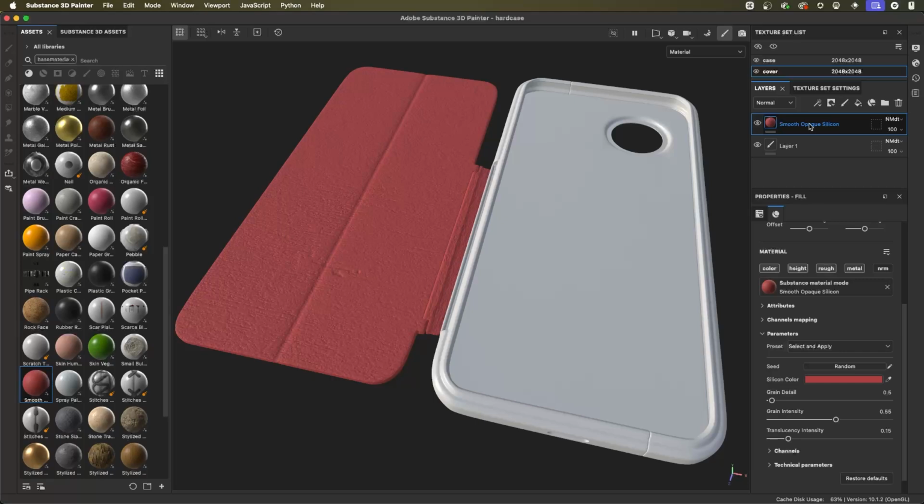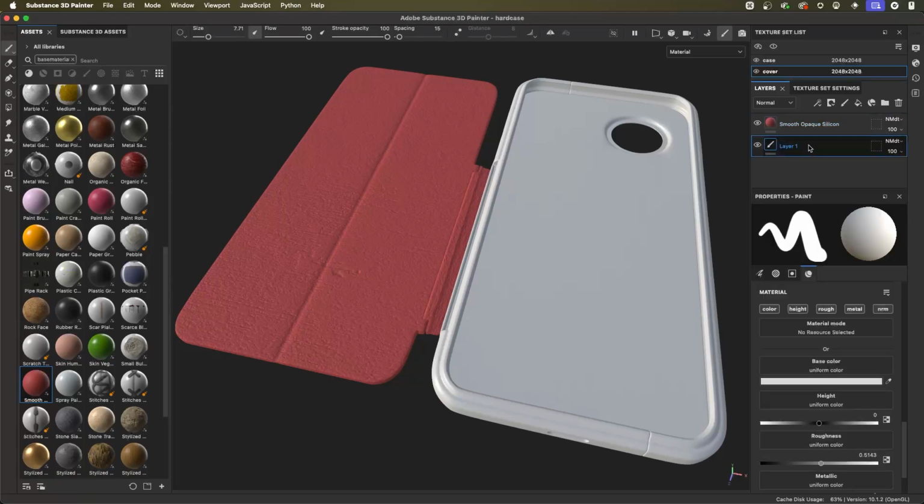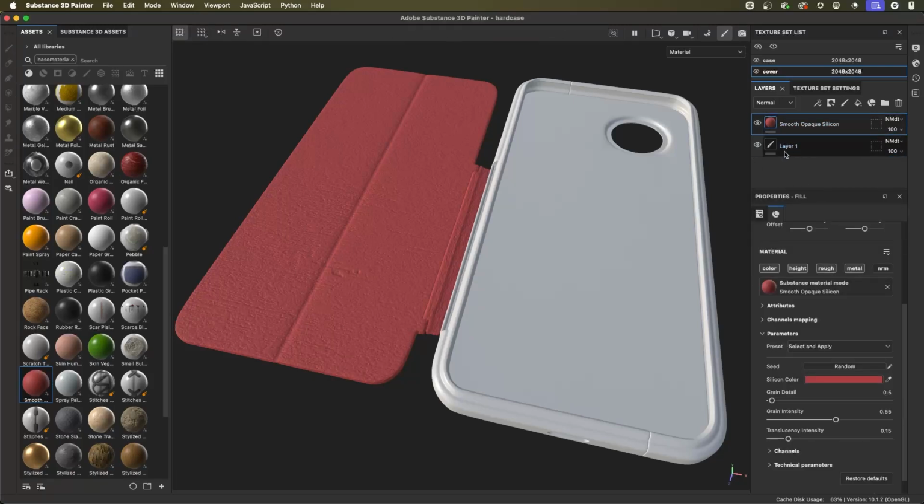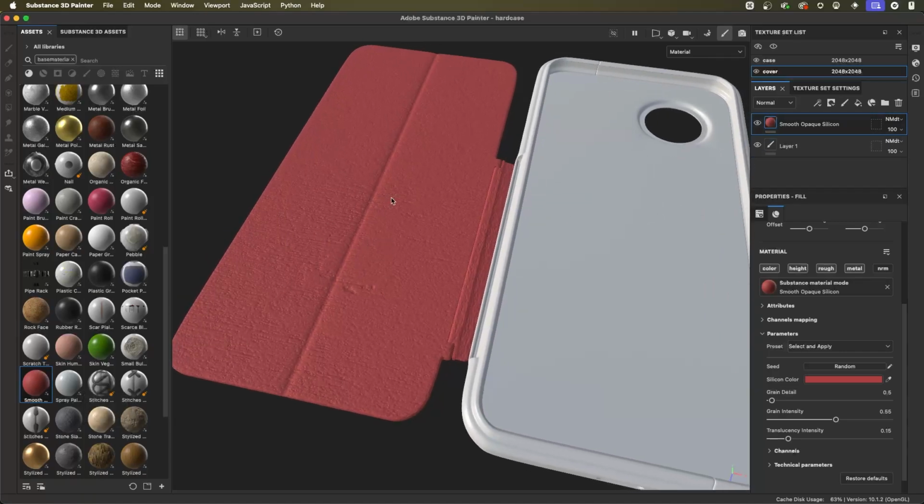This is that second type of material, or second type of layer that I had mentioned earlier before we got deep into the brush material settings here. So we have our paintable layer, and now we have this new material called a fill layer. Essentially what it does is it takes our material channels and just fills them with information, whether it be like a uniform color or some kind of data or a texture map. Just as long as it makes a material, that's all we really care about. So now I have this fill layer. Now, what's interesting about this is I can start to work with this. Like I said, this is a procedural material in the sense that I can change parameters.